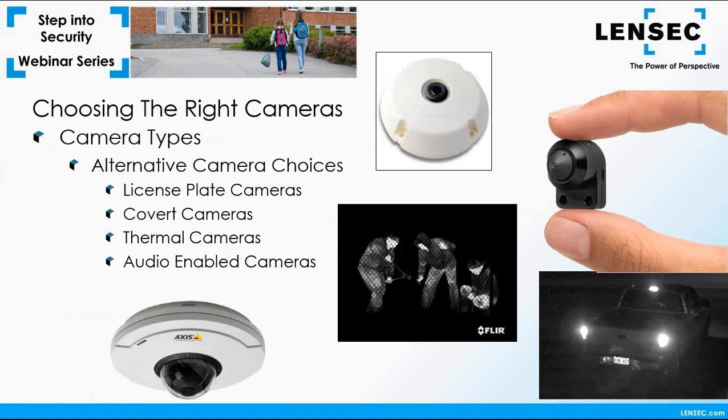Some security integrators will rely on megapixel cameras to get the license plate detail, though if you want to go that route, make sure you have enough light at the LP capture zone in order to get the detail you require at night. Also, narrowing your field of view at the capture zone will enhance your ability to make out the license plate detail. Placing the camera at a choke point where traffic narrows and slows down helps with the ability to capture your detail as well.